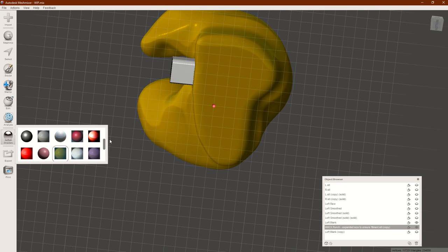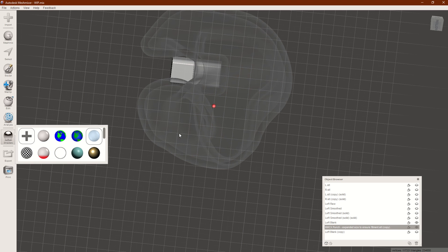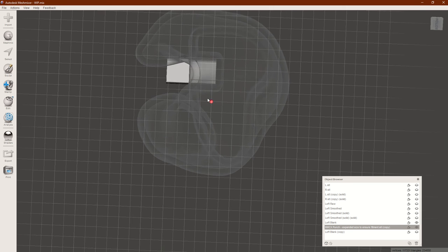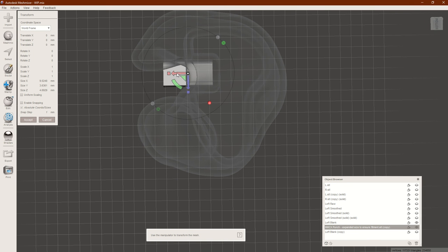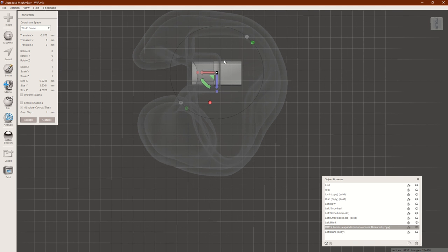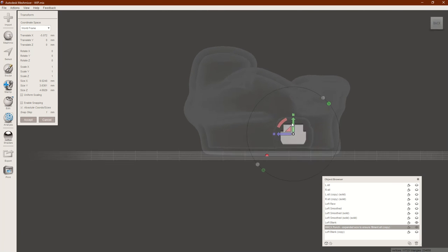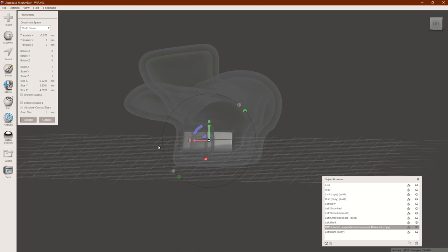So to do that, I hate this weird orange color. There we go, it's bright. And I'm going to do transparent, actually, on the shell to work with. I'm going to move this copy of this MMCX holding down T, and I'm just going to do it right along the axis, so it's exactly in line. I'm going to park it right in the middle of this solid wall, and you can see that if I were to Boolean difference, it would actually knock a hole through.